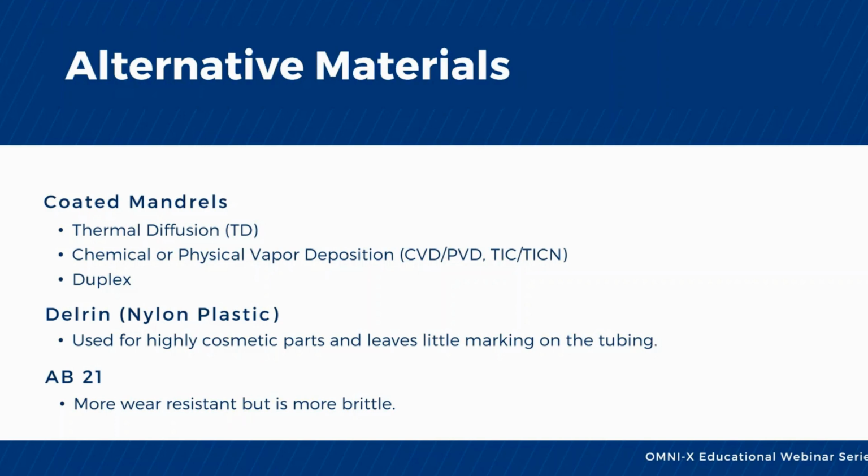One final word of caution on coatings. If your tube material is typically dirty, having a lot of debris and grit, then that will eventually lead to premature wear and failure of the coated mandrel. Since the cost is significantly more than a normal mandrel due to the specialized steel and coating process, this is something to consider if that can be managed to protect your investment.